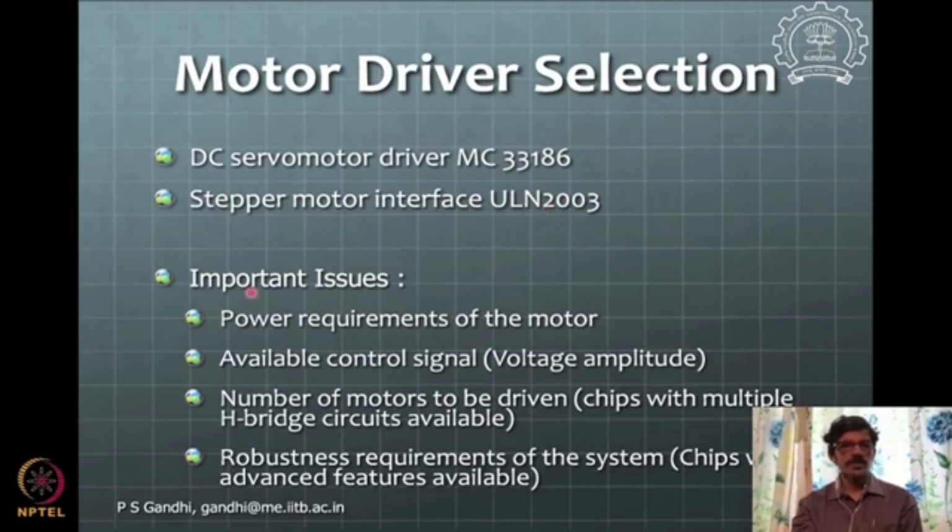An important issue to consider is the power requirements for the motor, and the available control signal, especially the voltage output amplitude. This power requirement and motor voltage compatibility should be seen. Not only power but voltage and current compatibility is to be seen.